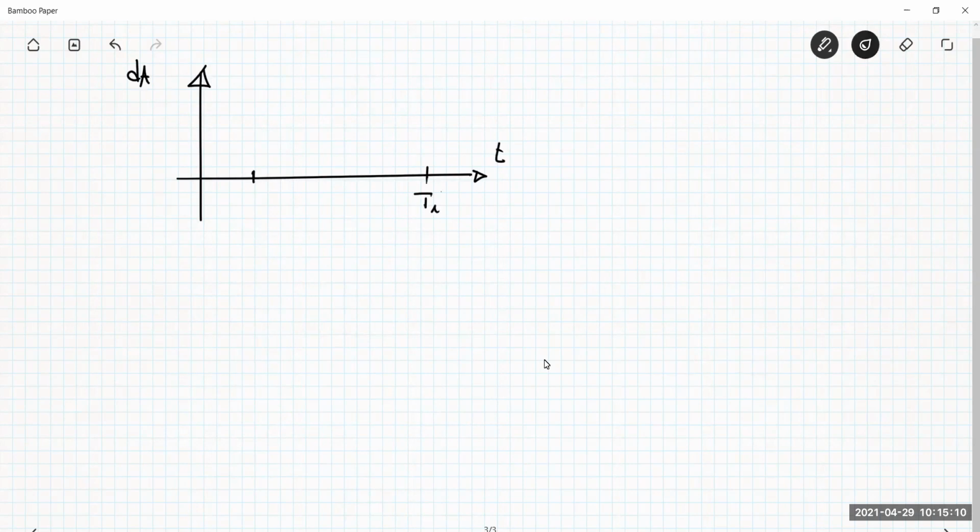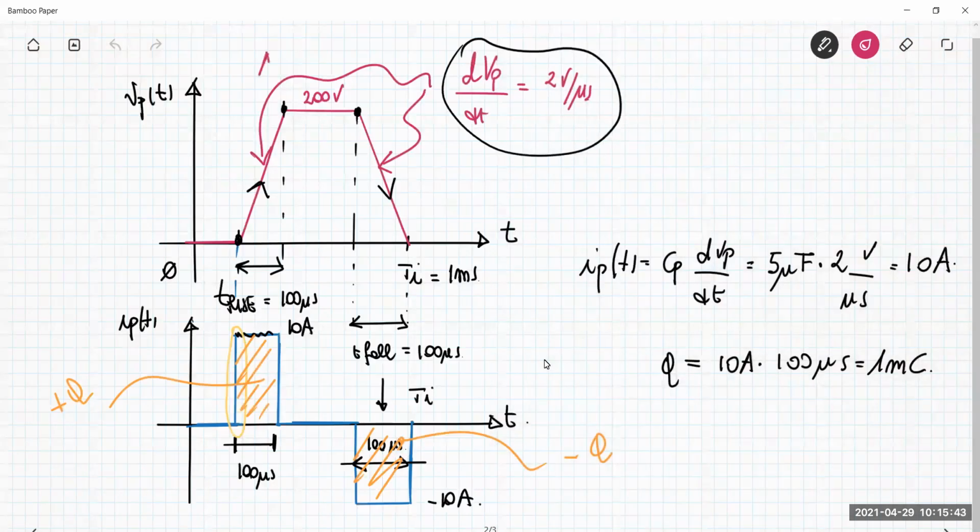So the duty cycle is something that increases from 0 to a maximum level. Suppose that we are adopting the strategy to use the transistor TA plus in the buck operating mode, and then leave the TA plus open for the rest of the interval. So we are just using, we call this A region.